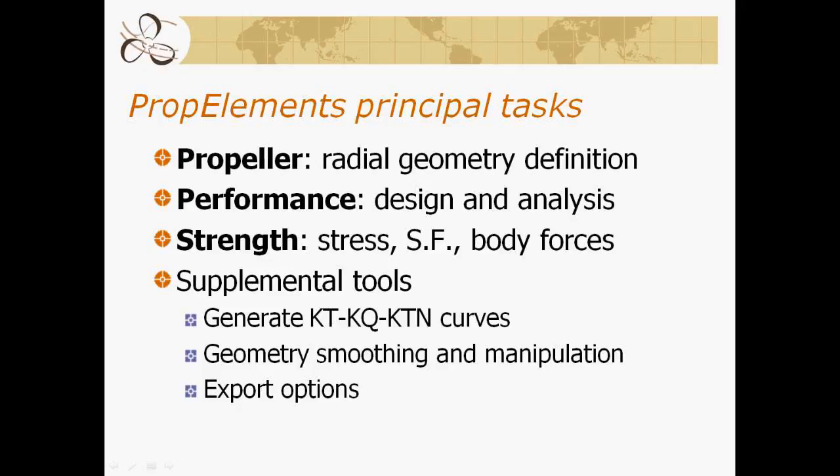Now, the principal tasks of PropElements, and I'm going to introduce just this here before we actually begin to run a sample calculation for you, is there are three principal page groups. We have a propeller page, which defines our geometry, the radial definitions. We have a performance page, which is where our design and analysis is conducted. And we have a strength page, where we can calculate stress, safety factors, and body forces.